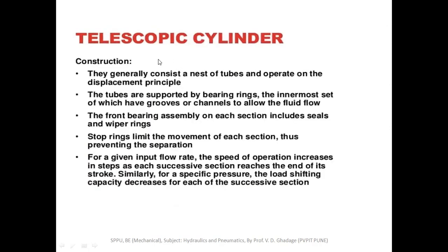So telescopic cylinder construction: they generally consist of a nest of tubes and operate on the displacement principle. The tubes are supported by bearing rings, the innermost set of which have grooves or channels to allow the fluid flow.